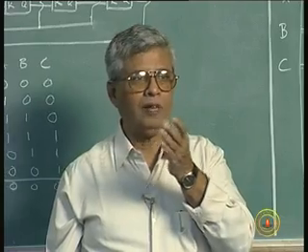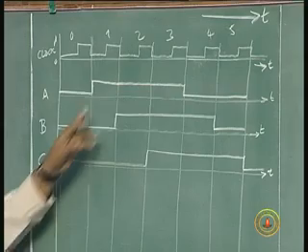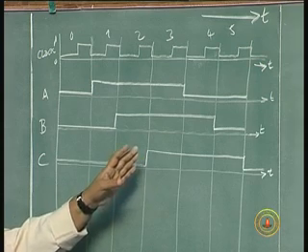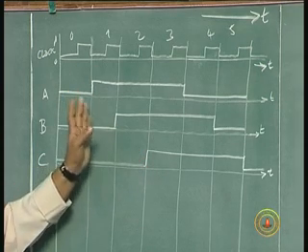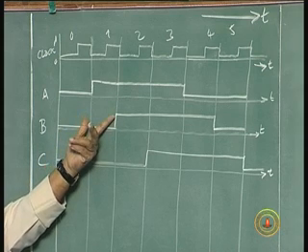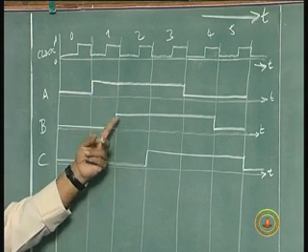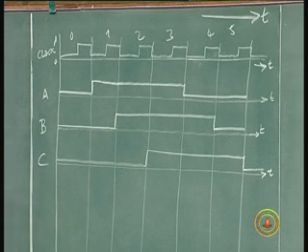That is one thing which you can always get by division, but more importantly, if you want to use these as separate clocks of different phases, there is always a phase difference of 1/3 of a clock period between this and this, this and this. I can get what is called a multi-phase clock.